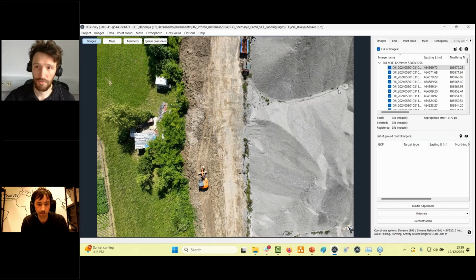So there was a question from Julia. Are the coordinates accurate? I'm not sure on what part of our webinar this question was posed, but the short answer is yes. Right, Marco? Exactly. If you do it by procedure as it should be done, it should be accurate up to 4 centimeters if you fly at 80 meters with standard drones.